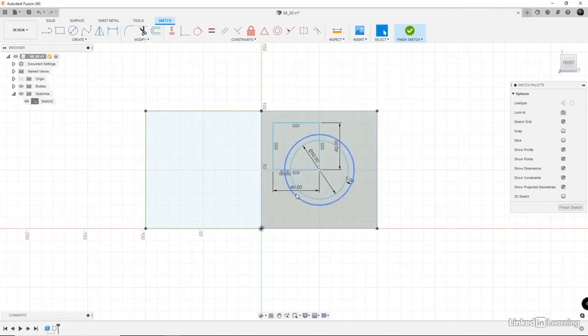I now have that sketch geometry that I had on the other surface, and I have it on the correct surface and moved back into the location that it needs to be into. So this is a really cool little trick if you need to move a sketch plane from one geometry to another geometry. This is a really helpful trick where you can move it quickly and seamlessly.